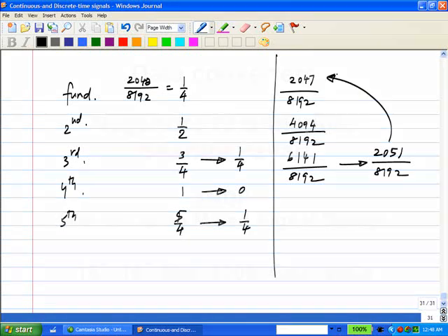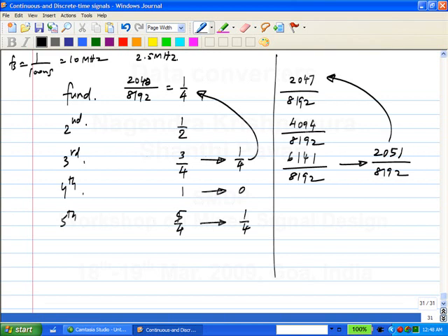So by making it very slightly separate, I am not changing the test in any fundamental way. Let's say my Fs was 1 by 100 nanoseconds, that is 10 megahertz. One fourth of that is 2.5 megahertz. Now this is also very, very close to 2.5 megahertz. It's not like I originally had 2.5 megahertz and now I test it with 100 kilohertz, a totally different performance. I still have something very close to what I want to test, but I have taken care that the harmonics don't alias on top of each other.